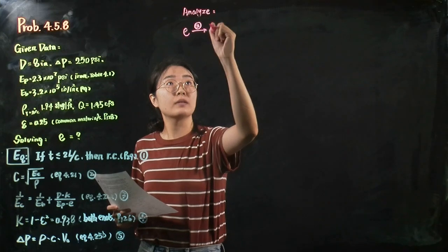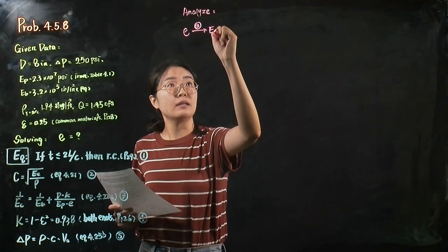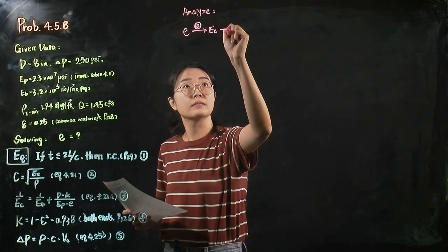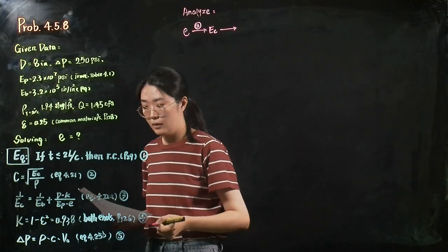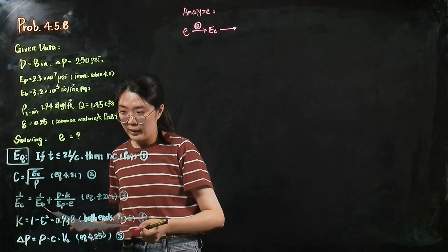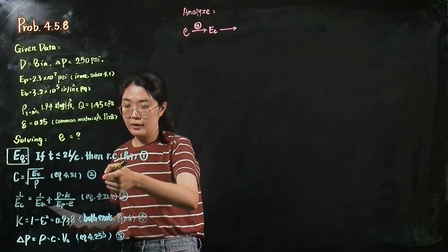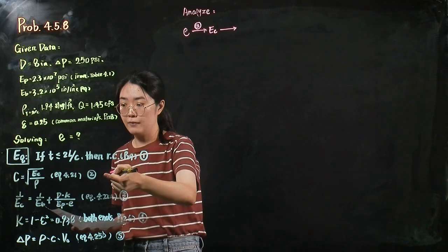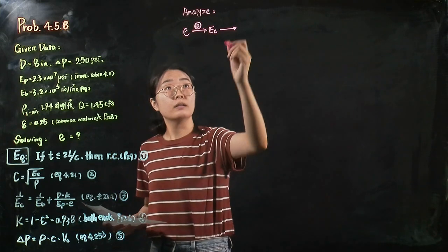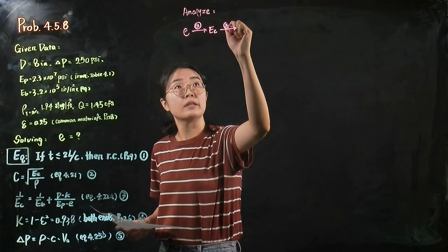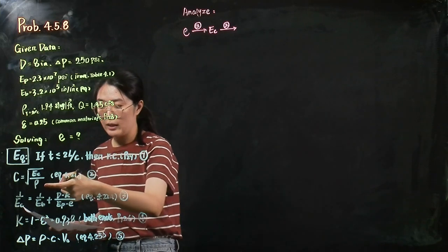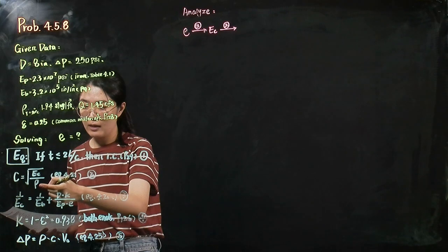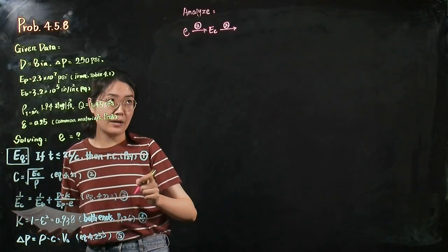we need to get the value of the composite elasticity of the system first. Therefore, we need equation 2 to calculate the composite elasticity of the system. In this equation, the water density is already given, and we need to calculate the celerity.